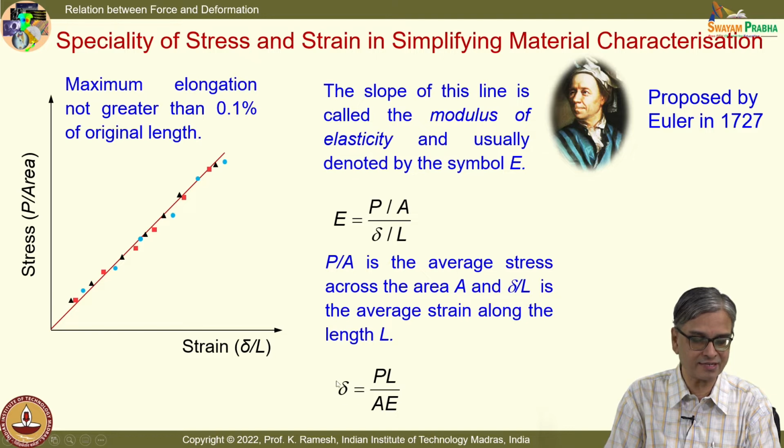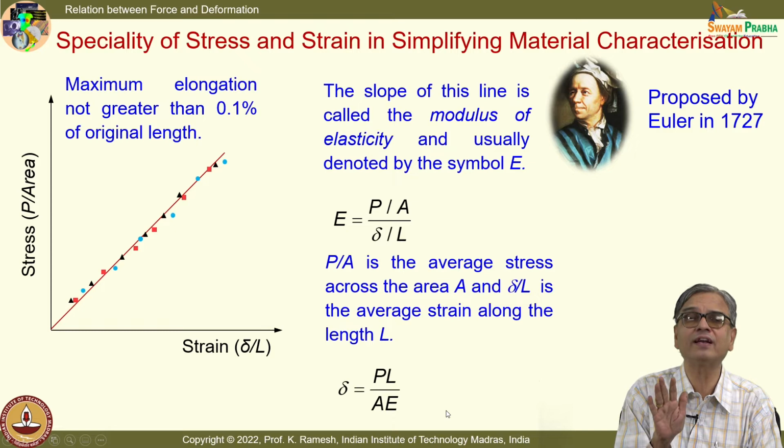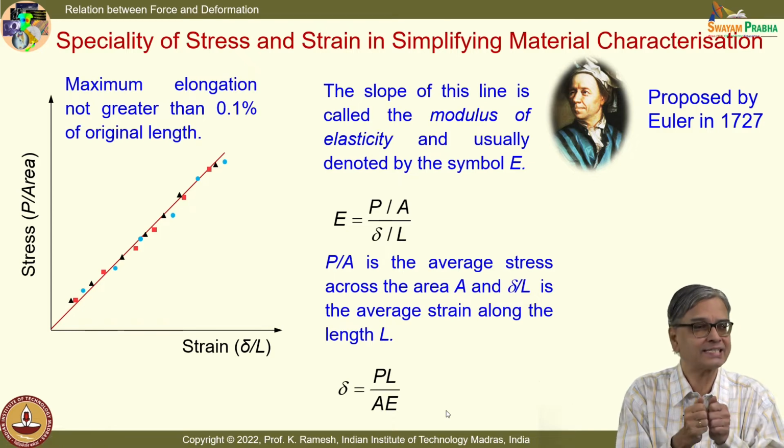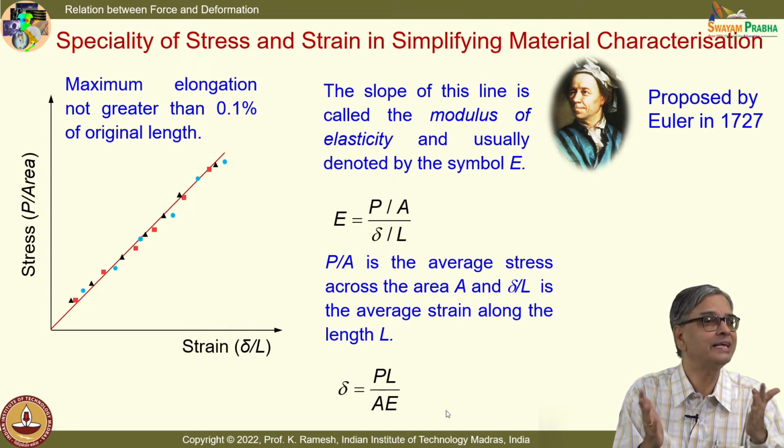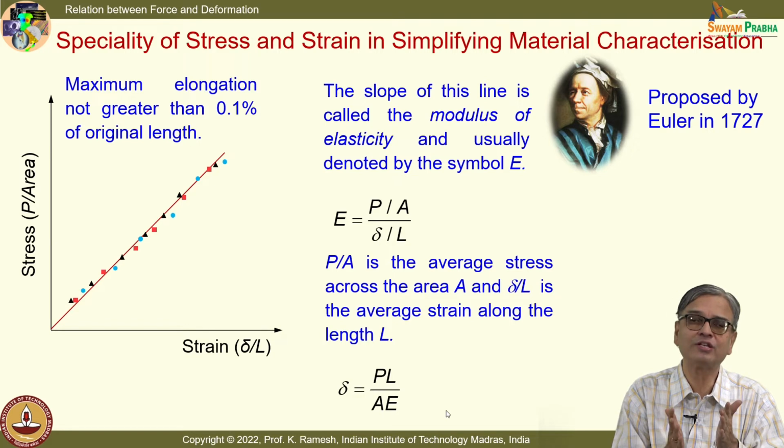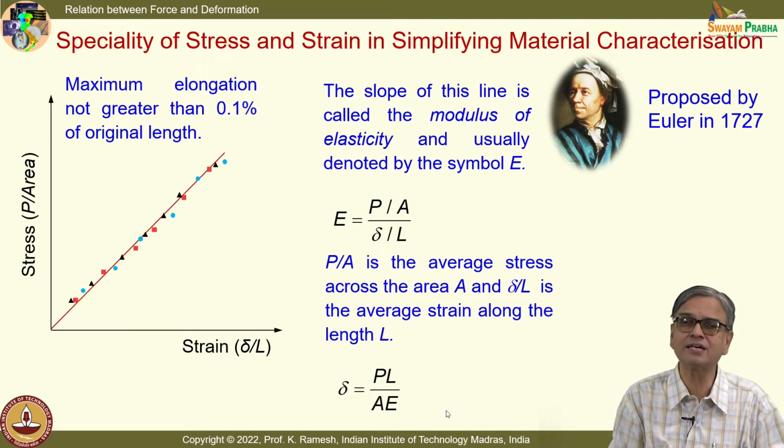I have this displacement as PL by AE, a very useful relationship. In an axial pull, the deformation, the change in length, is nothing but PL divided by A into E. We will use this to solve certain simple day-to-day problems.